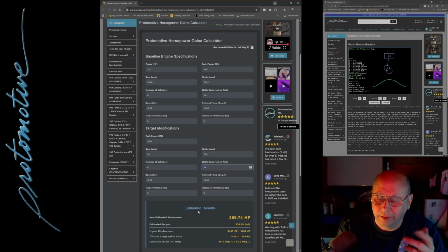It's got to work with your fuel, your octane, your build, your camshaft. You can run more compression when you have bigger cams in there because you're blowing a lot of the combustion out with the exhaust valve really opening.